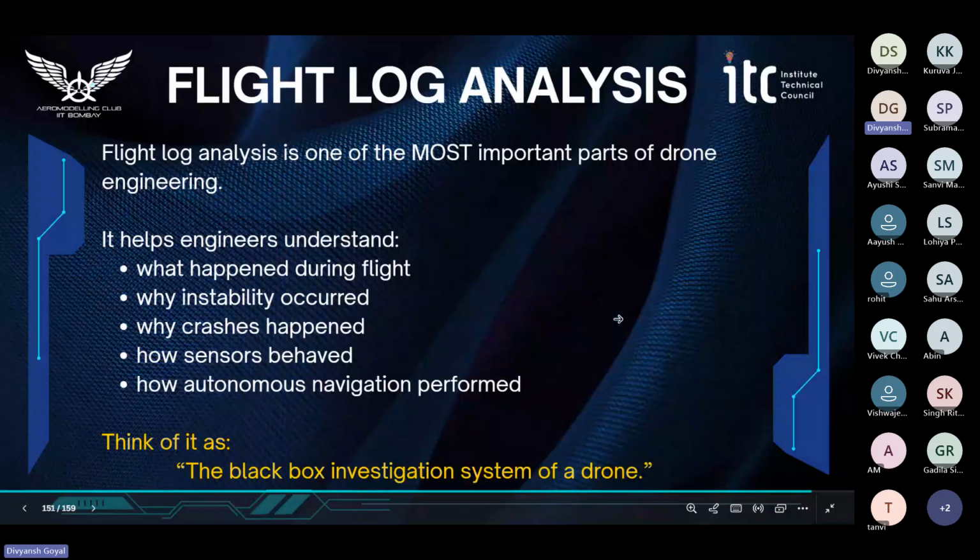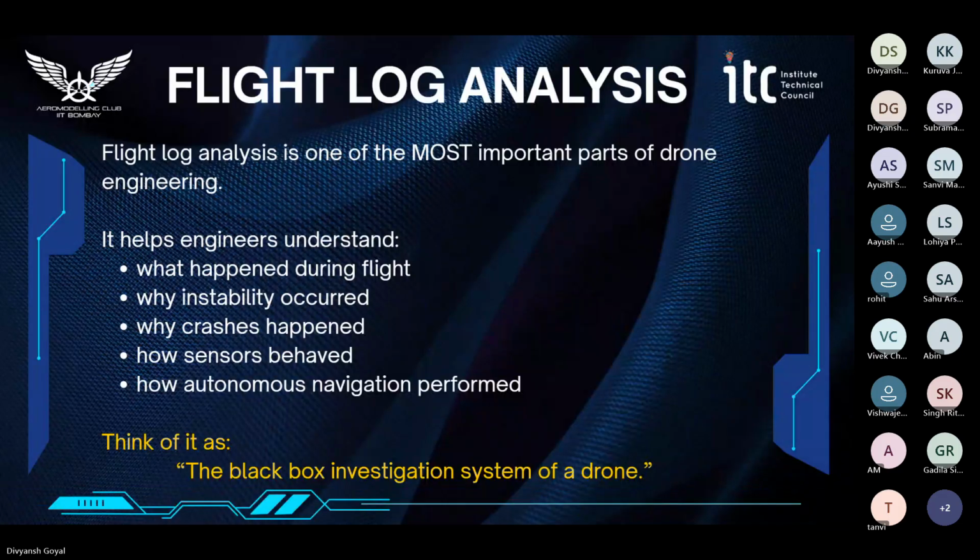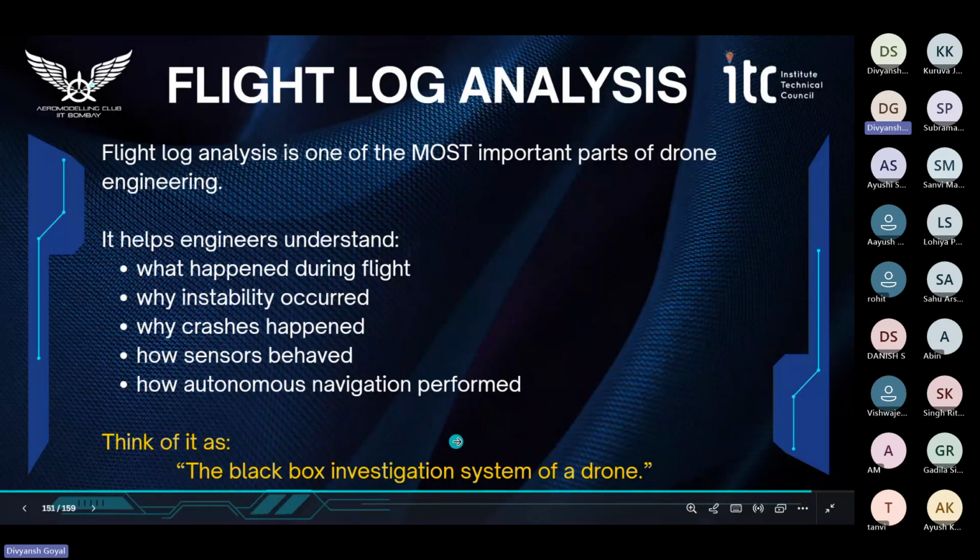And flight log analysis is really important because it helps us to understand what error caused our drone to crash. If your drone has crashed, you have to identify that error, and for this, flight log analysis plays a major role. It helps engineers to understand where instability occurred, why the crash happened, how our sensors behaved, and whether there is any kind of error in our sensors or the inputs that we have given. Yeah, it is like a black box or investigation system of a drone.